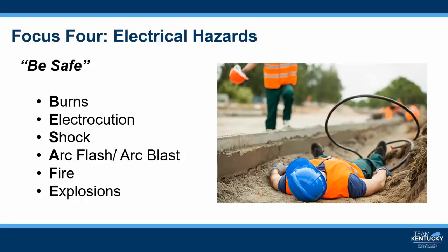The F stands for fire. Most electrical distribution fires result from problems with fixed wiring or faulty electrical outlets and old wiring. Problems with cords, such as extension and appliance cords, plugs, receptacles, and switches, also cause electrical fires. An arc flash can be spontaneous, or it can result from inadvertently bridging electrical contacts with the conducting object. Other causes may include dropped tools or the buildup of conductive dust or corrosion.